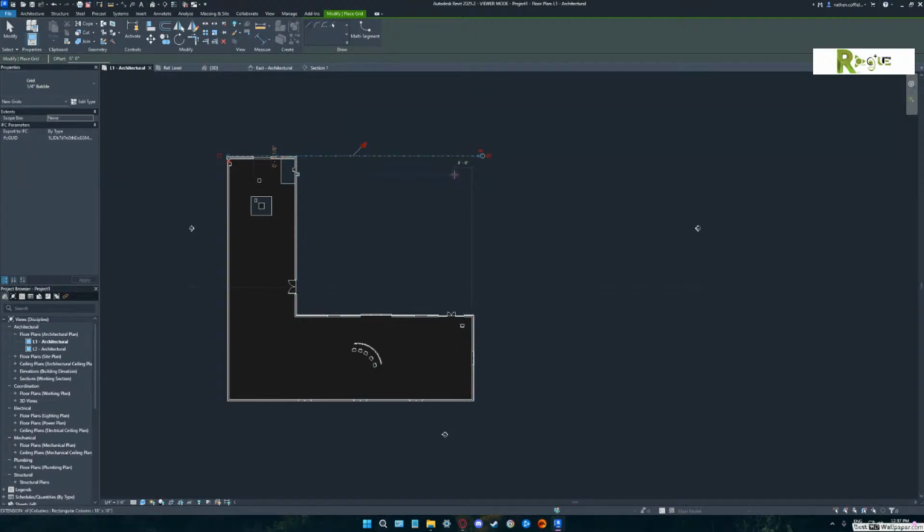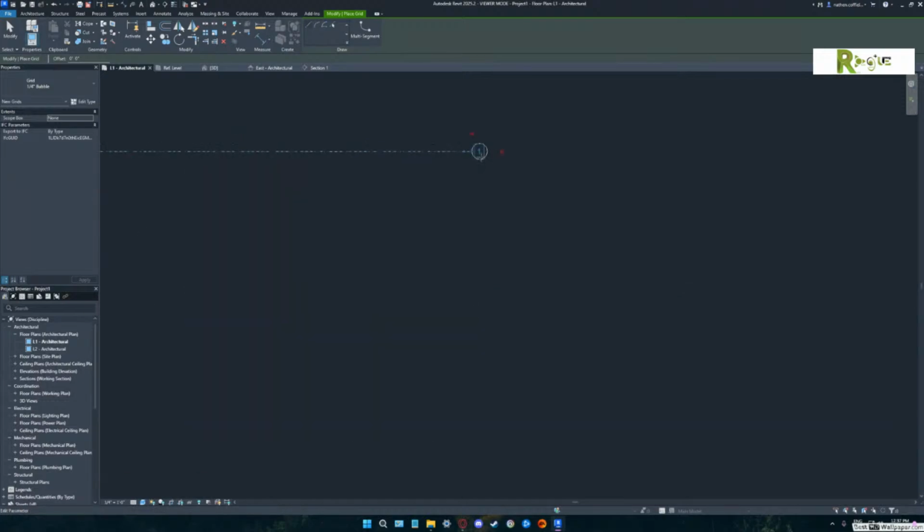But you got to understand, typically what would happen is when the person was drawing those column lines, they would pick those out to be centered around a certain spacing. In other words, you don't generally make those weird numbers. They end up being 16 feet, 16 feet, 16 feet, 18 feet, 16 feet. But what I want to show you is zoom into that bubble that was actually drawn. Right now it put a number 1 in there. I want you to change that to a lowercase a.